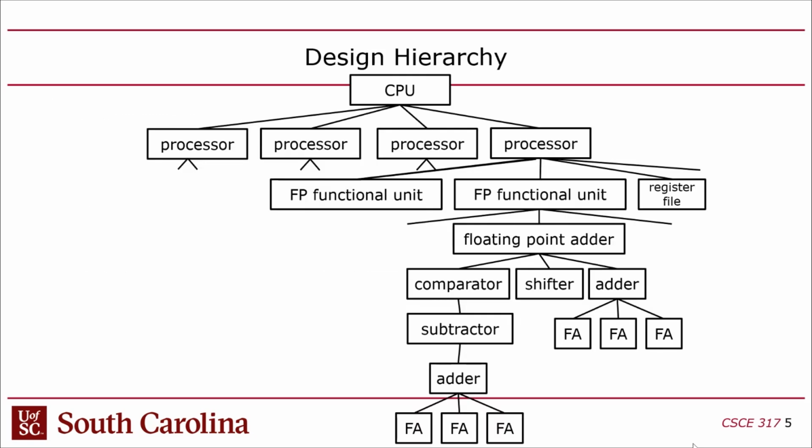And as I mentioned, I'm just introducing it in this class. I just want to teach you enough of it to write a simple module that we can put into Platform Designer to control the LEDs, so we don't have to use software for that. So I mentioned that there's a design hierarchy. The module is the foundation of the hierarchy, because modules can be instanced in other modules. More abstract modules are at the top of the hierarchy. The less abstract ones are at the bottom. They're the leaves, and those tend to be more behavioral. Those have logic in them, whereas the ones higher in the hierarchy are just instances of other modules.